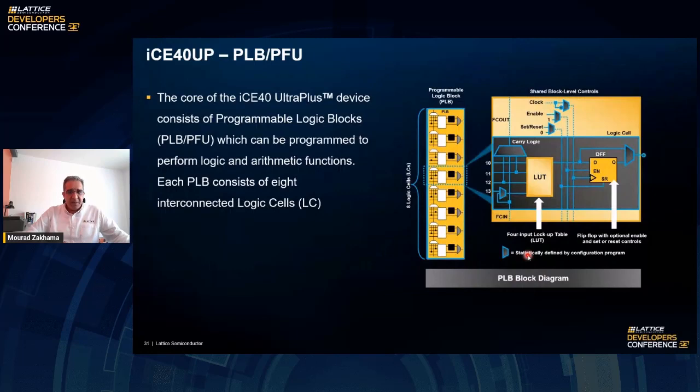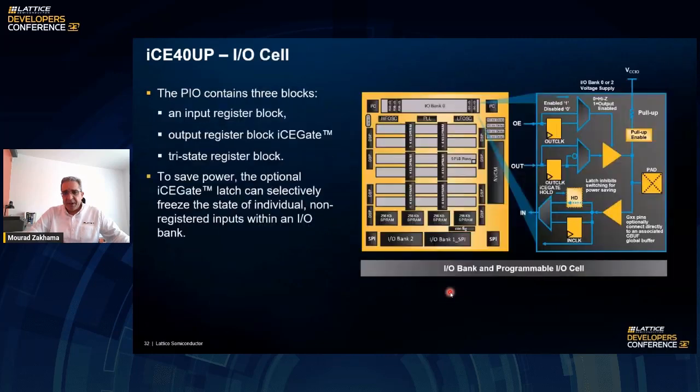So if we look at the PFU, and this is the real architecture from the data sheet, you're going to see each one of these PFUs, like I said, is a 4-input lookup table plus a flip-flop, but you're going to see some carry logic going across the different logic cells that you have in the design. There's the register, there's the option to bypass the register, and there's the input for clock enable and reset that is shared across the PFU.